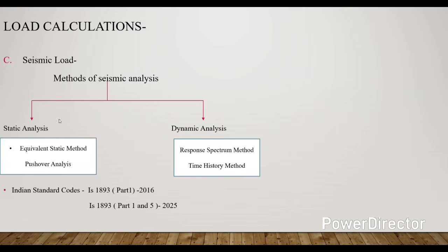Now the reason is that I have just introduced these methods in the slide. In this video we'll concentrate on the equivalent static method and response spectrum method. I have defined the parameters of the earthquake load in ETABS, that is EQX and EQY, according to the equivalent static method. Okay, and I will also show you how the response spectrum analysis is done in ETABS.